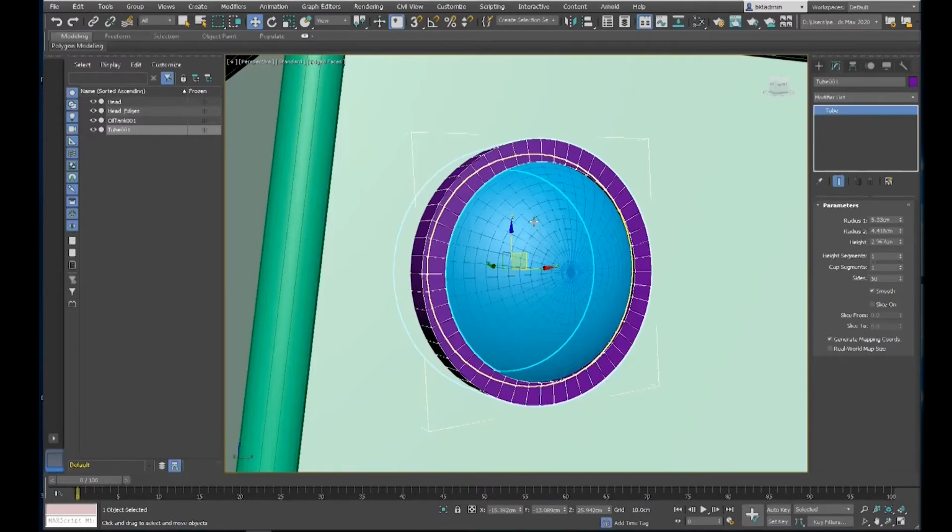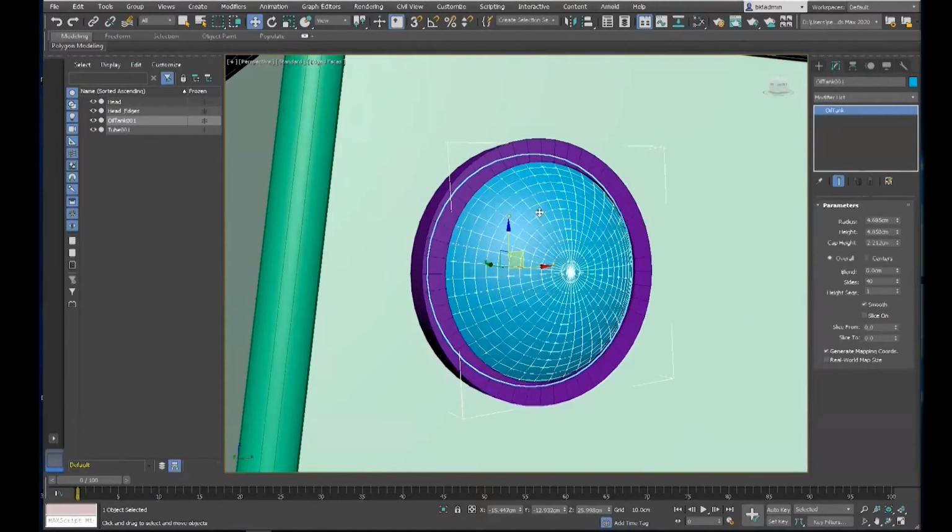But if you have a robot army and you have 1,000 robots with the same head, even if the resolution is fairly low, it could be demanding. And especially if you want to animate them in real time, then you should take care of the resolution a lot. So one way is to delete those polygons you don't need. And this is what we will do now.